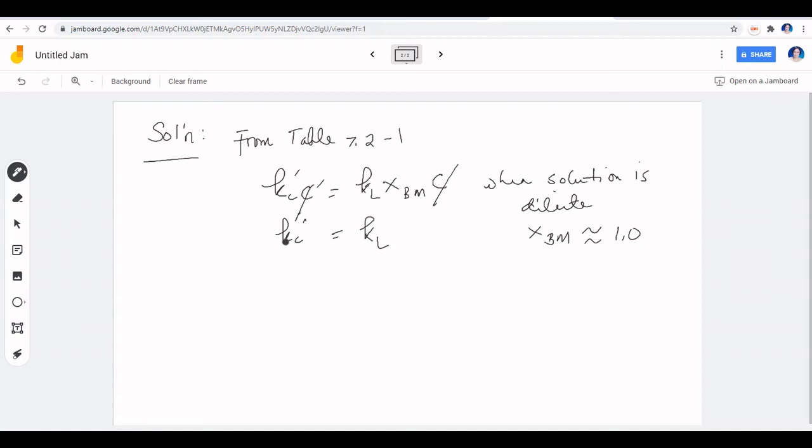But before we can even use this particular formula, we need to establish the velocity profile, or determine whether flow is laminar or turbulent. Specifically, we need to know the Reynolds number so that we can check in what particular range it falls. So in this case, we need to determine the Reynolds number.